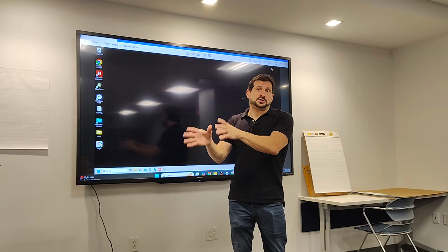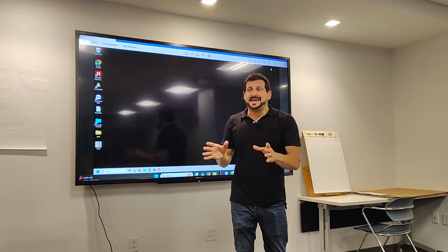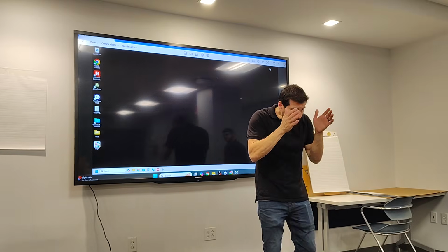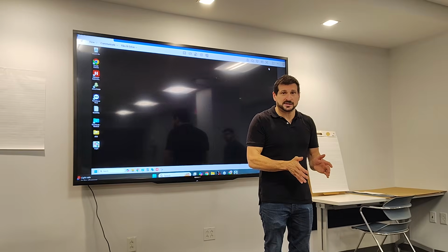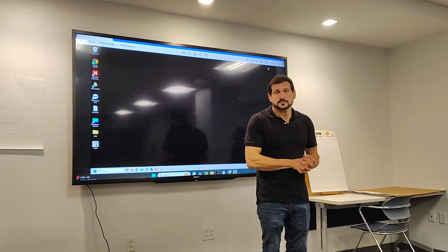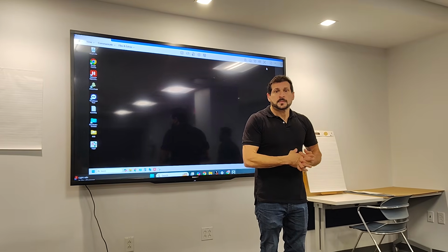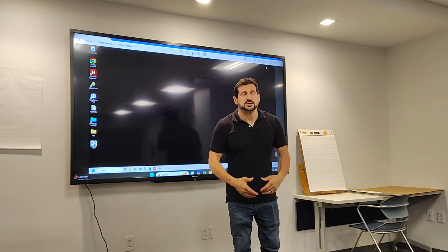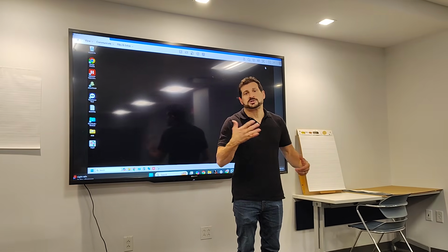So we don't want to touch valves, we don't want to touch outputs unless we have to. We never want to touch inputs. We only want to interact with virtual points. Does that make sense? It means I leave everything automatic, but in the worst case, I can do it manually. That's the idea. You want to leave it automatic, and in the worst case, do it manually.